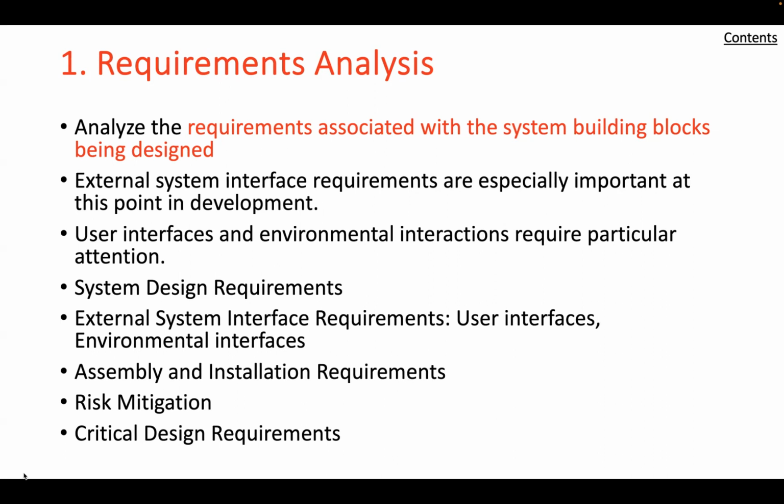System installation aboard aircraft is another example. Each building has load and size limits on freight elevators. In any case, when on-site assembly is required, the system design must consider where the system will be cut and how it will be reassembled. If physical mating is implemented by bolts, for example, then the location and size of these fasteners must be taken into account in the size and position of the wrenches needed for assembly.